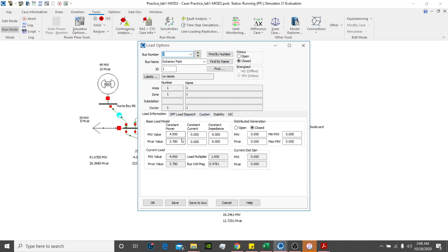And each time you vary them, you record the per unit voltage and the load angle. By load angle, I do not mean the phase angle. I mean the voltage and the bus bar angle. That was a major issue as stated by Dr. Isaacs, so just for the orals, it's good to know.